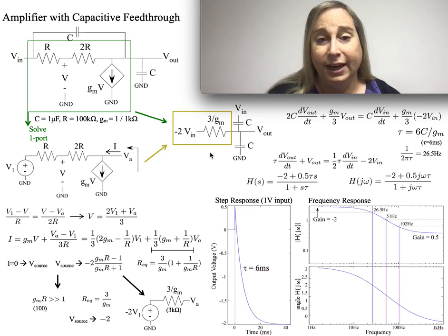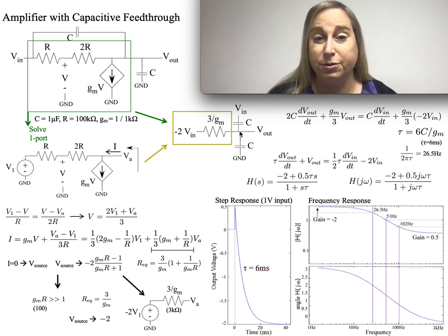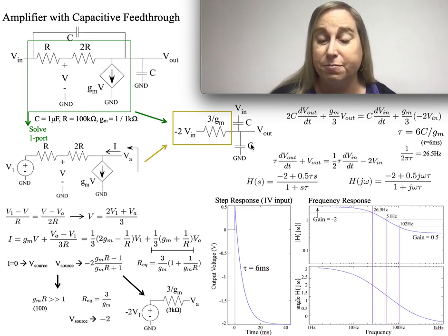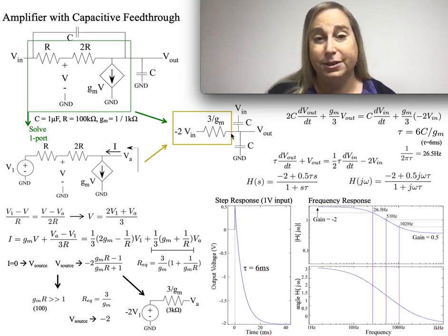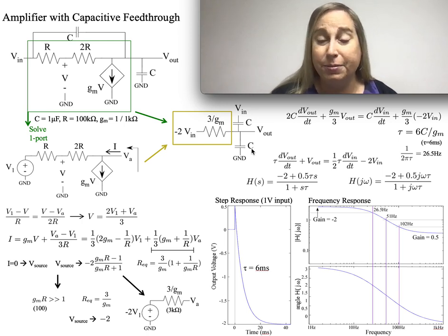But it still turns out that I have 1 node that is basically first order. It's a first order structure, just resistor and capacitor, nothing particularly crazy. But one thing to notice is that from V in to V out, if I don't pay attention to this resistance, this is a capacitive voltage divider, and we know that gain is going to be a half because I've made both C's equal. So I'm expecting that's going to probably show up in this conversation.